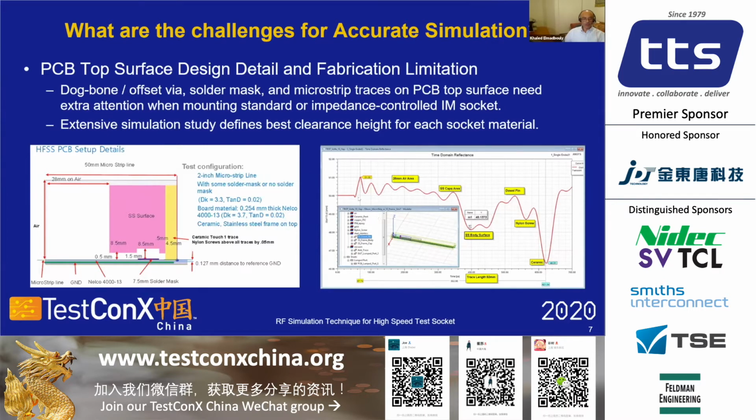So we ran a lot of analysis using different materials on the socket or the probe head: aluminum, stainless steel, dowel pin, nylon screw, different plastic materials, ceramic, Vespel. We use this model to find the optimum performance, what would be the best gap, and we recommend our footprint to the customer to avoid any signal integrity degradation from having the socket or the probe head sitting on top of the microstrip traces or some power via.